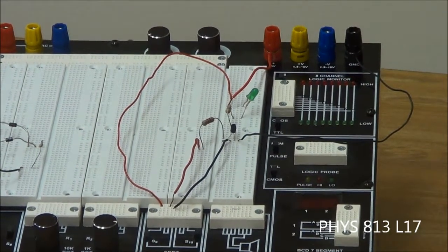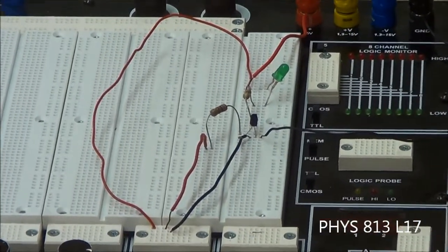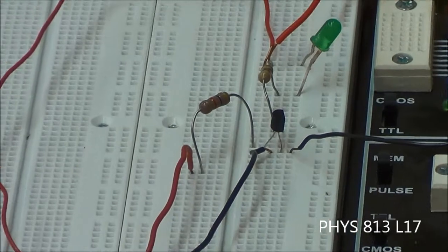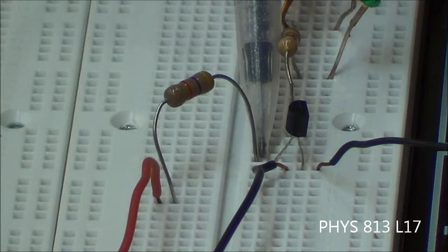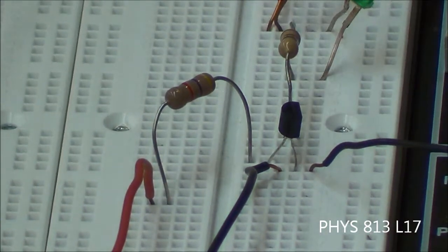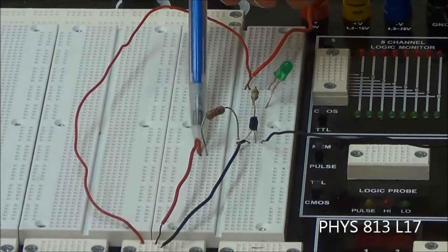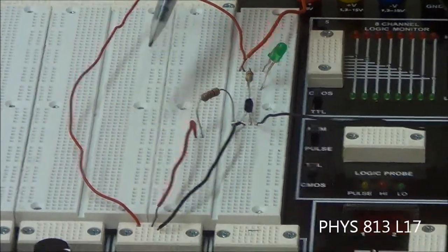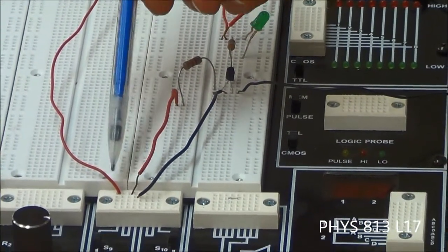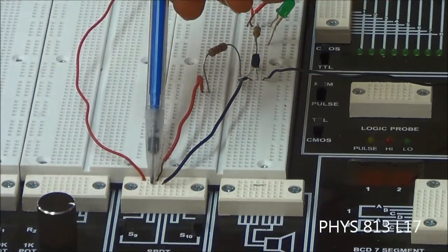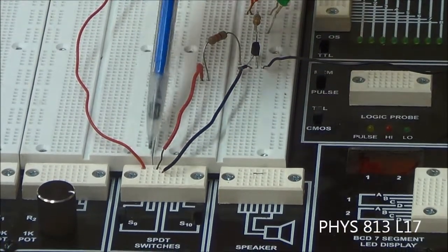Okay, so then the next thing I did was the base resistor, which is the 4.7 kilo ohms, the yellow, violet, red. So we have one end of it into here, and then the other end needs to go to the middle of the switch. So I put the other end over here in this other region, and then got another wire to go from it to the middle of the switch. Remember that there are two middle columns that are equivalent, so you can use either one of those.